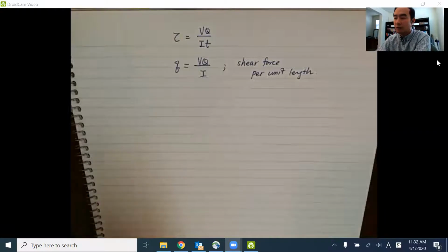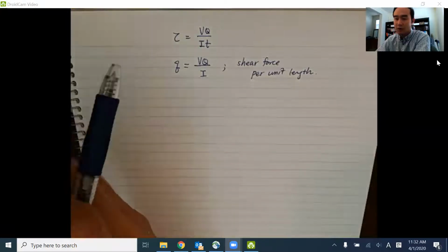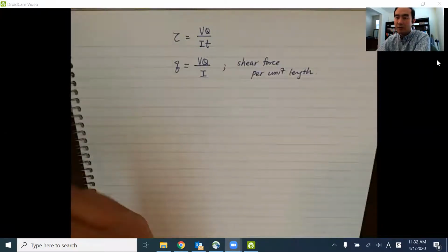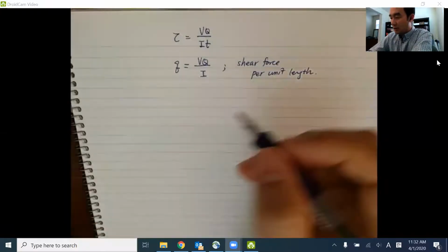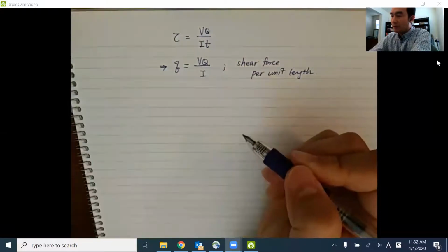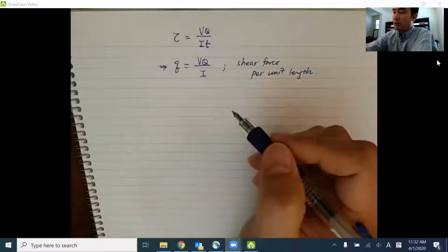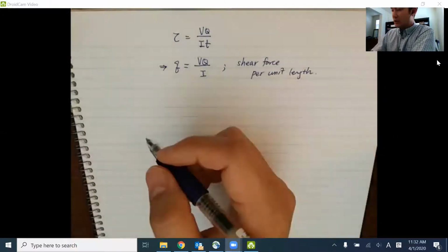And we have to have an understanding about how much force is going to be applied to this member so that we can determine how many nails are required or how strong the glue is going to be required for these sections, right? So that's how we can apply this concept of shear flow into real world problems. So we're going to talk more about this through example 12.4.